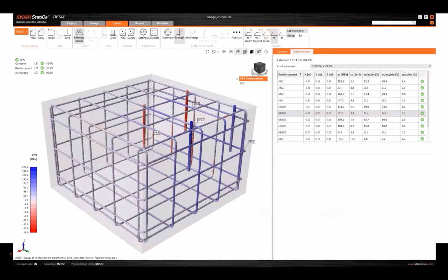We have it in-house, so we are supporting this BIM link. We are fixing the bugs and so on. So this is a really big step forward for analysis, design, and code check of every shape of the anchorage block, with different modifications of the reinforcement that is inside. And we are also capturing the failure modes like pulling out of the concrete cone, or pulling out of the rebars or anchorage from the concrete block. So everything is captured there.